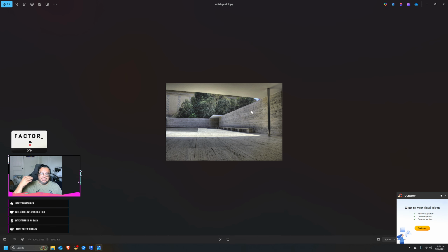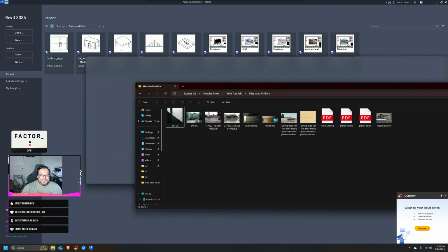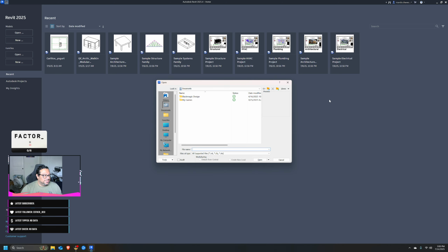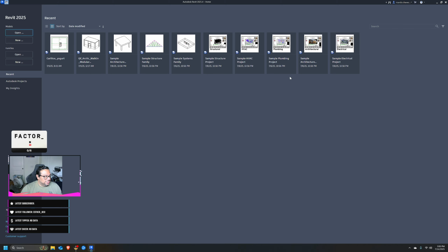We're focusing on the building blocks of Revit, and then in future videos we'll start with what you're going to use in a real work setting, right? With any job, if you're working in a professional office, you might open Revit here, and there are 2 different methods. If your company's not on cloud services yet, your models will be saved to the server. If you go to Open, it'll ask which file you want to open. Usually, you never want to double click a central file.